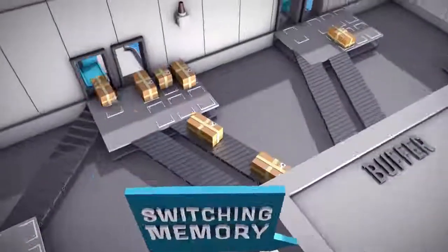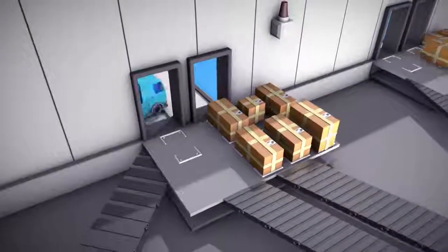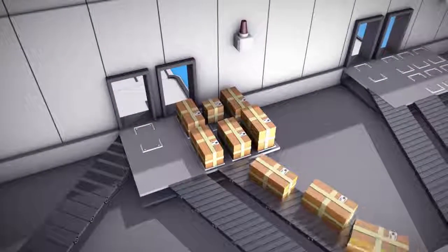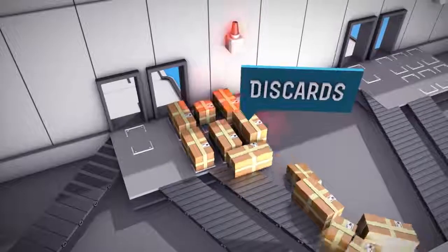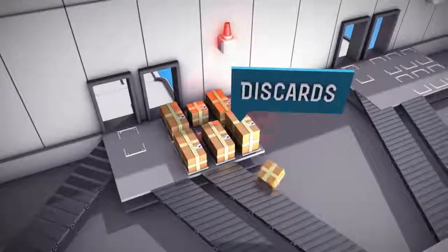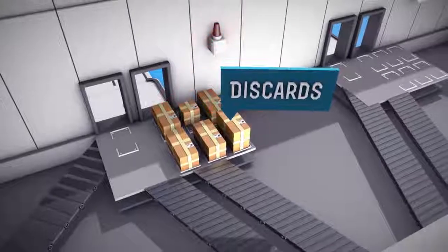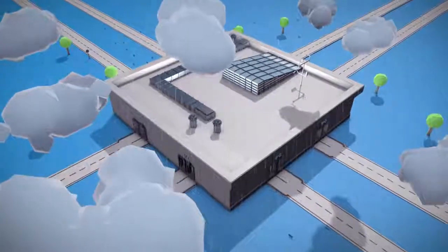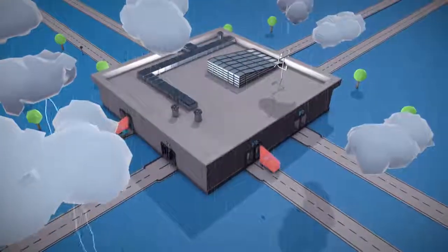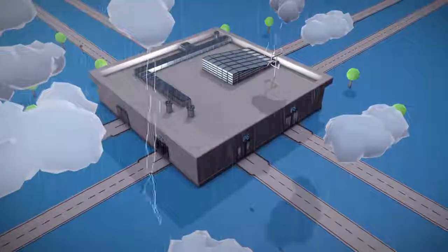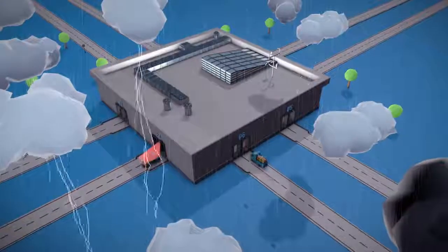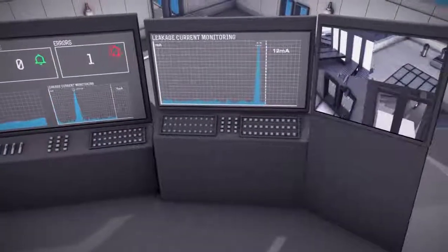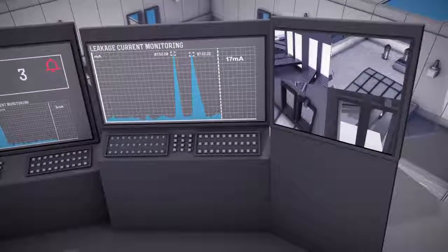Frequently, telegrams from several input queues are almost exclusively routed to one port, for example to the backbone or the controller. This results in its output queue becoming full and all new incoming telegrams being lost. These so-called discards are a sure sign of unstable network communication. In mechanical engineering and plant manufacturing, unwanted leakage currents often occur on the data line shielding, comparable to a thunderstorm. They are a strain on telegram traffic. A good switch can withstand these EMC influences, monitor them, and report rising loads.